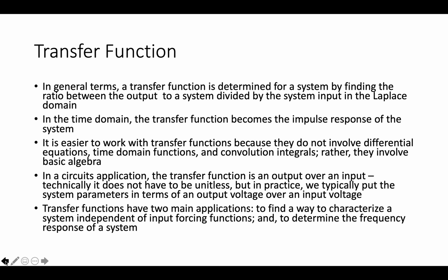I should at this point mention that when we find the transfer function of a circuit, we do not have sources in that circuit. It's just going to be a network of resistors, capacitors, and inductors. You can also find a transfer function of a circuit that contains an op-amp, and we'll do that later as well. And you've probably already done something like a transfer function in circuits when you calculated the output of an inverting amplifier, because you could get a ratio of output over input.